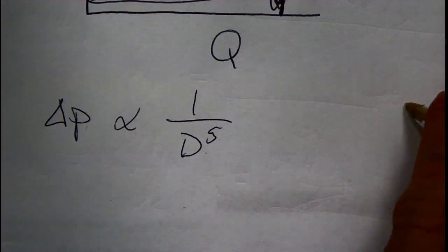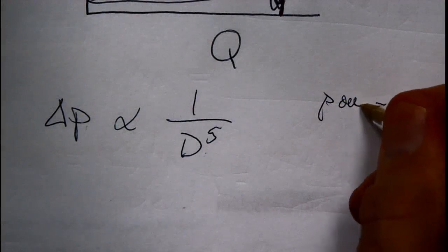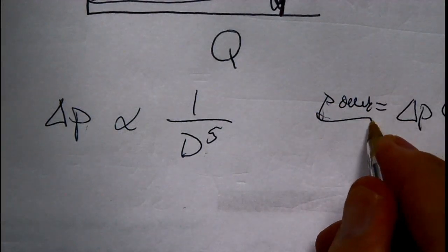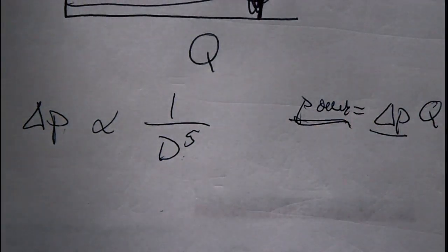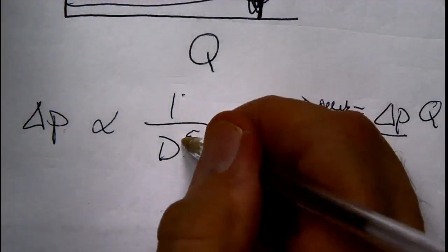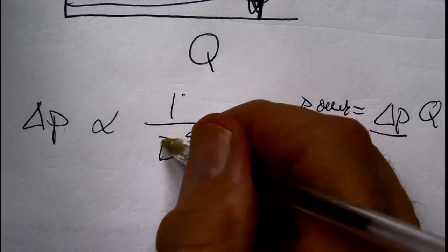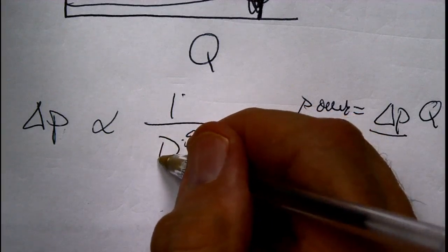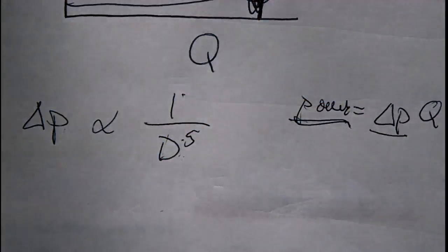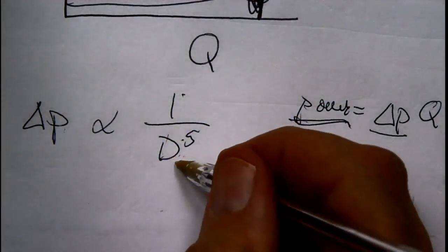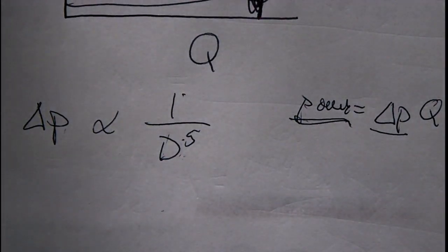Since the heart is only putting in this much power, and this is limited, the power input limits the available pressure drop. So you find out that if you have a very small artery, or a blood clot, or an accumulation of plaque inside the blood vessel, and this diameter gets smaller, that means pressure drop goes through the roof by a fifth power.